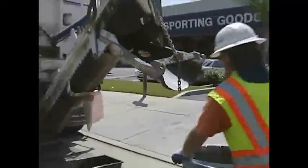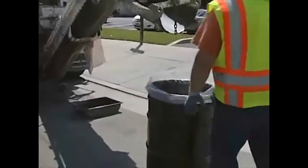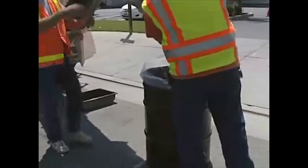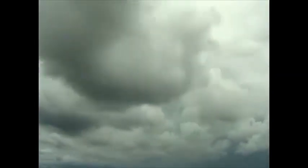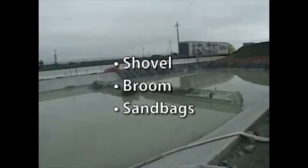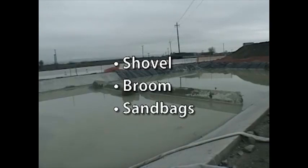In the event of concrete washout overflows, discontinue using the washout and construct a new facility to contain the anticipated washout operation wastes. Provide temporary containment to collect wastes that are generated when pumps and transfer hoses are cleaned out away from the washout. Ensure that the washout is covered during rain events. Ensure that a shovel or broom and sandbags are readily available at the washout facility in the event of spills that may occur around the washout.